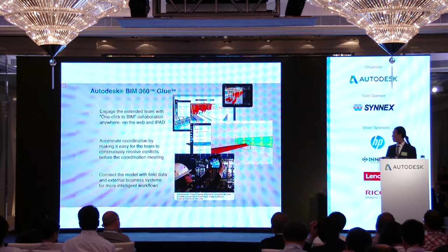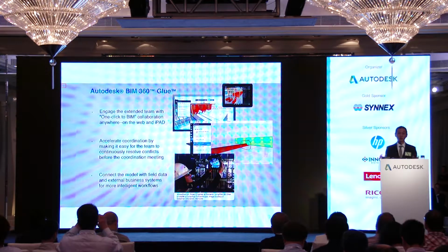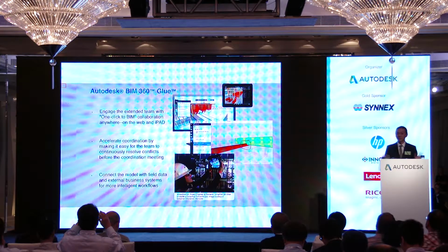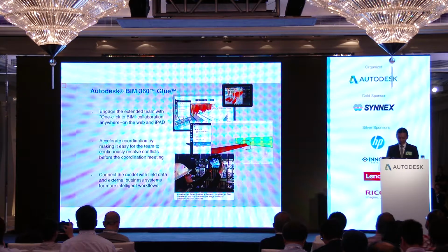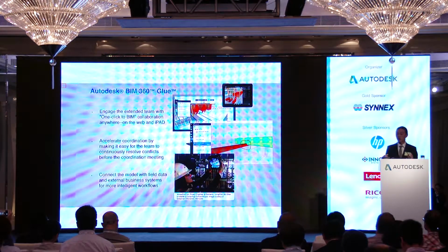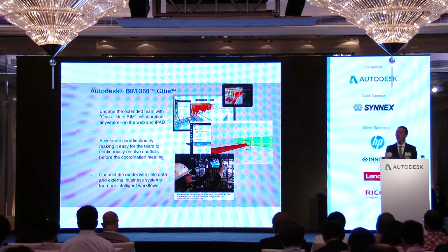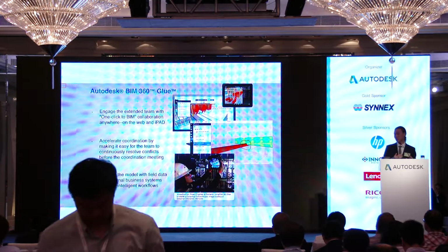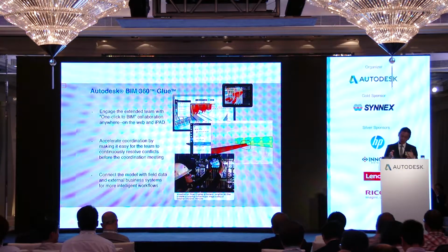I'm going to show you a little live demo of one of the projects that I've been using, just a quick one, keeping it low profile, because sometimes I can't show it. It can run Clash on the PC. Once it runs Clash, if you mark up all the criticals, everyone can see the same clash on the iPad. Once the clash has been solved and you refresh it, the marker will still be there, but you can see the clash is solved, so you can close the case as well, because it's all logged. You can track back why it's been changed, what's been changed, how much has been changed, because you can pull back a different version of the model.